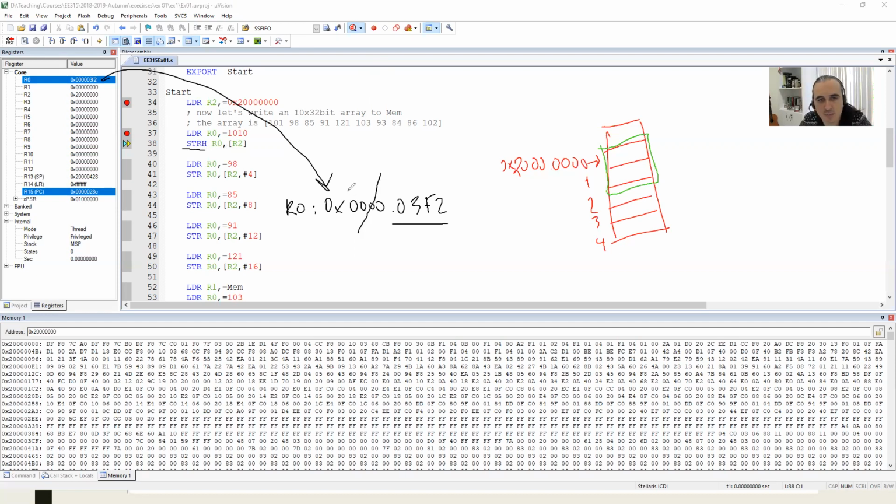So forget this part. I'm not going to be using it. And since this is a 16-bit, it's going to be using 2 cells in the memory. So this time I'm going to be writing F2 to the least significant lowest address because it's little endian still, F2, and 03 here, but not changing these values.